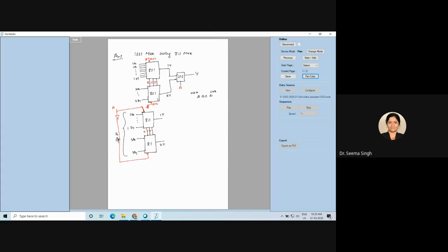Now what will happen? For the first 0000 to 0111, 0 to 7, A will be 0. Because A is 0, this will activate the first multiplexer, and 1Y will be 1D0 to 1D7.